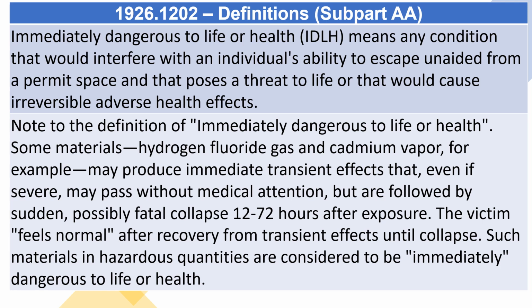Note to the definition of immediately dangerous to life or health: Some materials, hydrogen fluoride gas and cadmium vapor, for example, may produce immediate transient effects that, even if severe, may pass without medical attention, but are followed by sudden, possibly fatal collapse 12 to 72 hours after exposure. The victim feels normal after recovery from transient effects until collapse. Such materials in hazardous quantities are considered to be immediately dangerous to life or health.